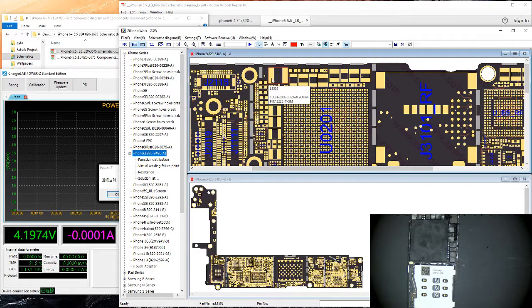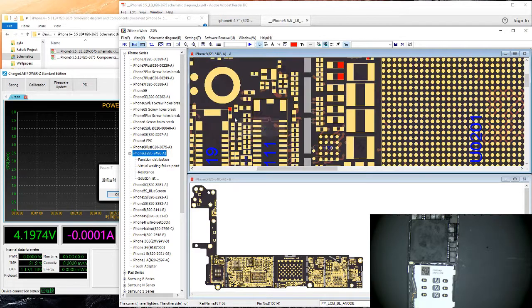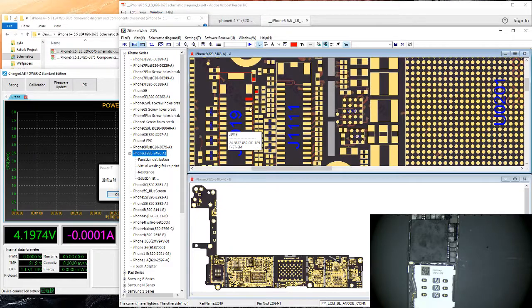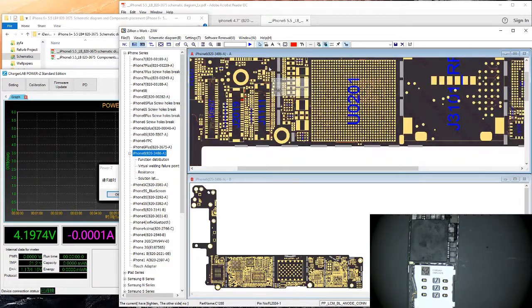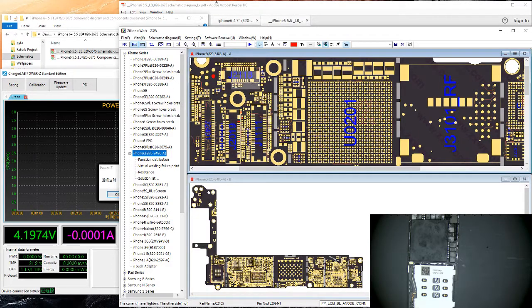They feed into this coil, which goes into the diode, half of the diode at least, main power supply. And then the other side is your anode, which is your main backlight power. Goes through these three caps, this little tiny cap here, goes through a little filter, which is just basically a fuse, and then to the screen. There's not a heck of a lot to it.